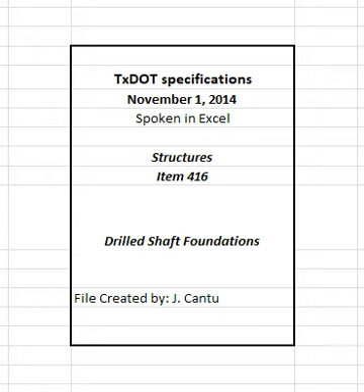Use casing strong enough to withstand handling stresses and pressures of concrete and of the surrounding earth or water, and that is watertight, smooth, clean, and free of accumulations of hardened concrete. Use construction methods that result in a minimal amount of disturbed soil being trapped outside the casing. This does not apply to temporary undersized casings used to protect workers inside shafts or to drilled shafts designed for point bearing only. Leave casing in place only if authorized or shown on the plans.